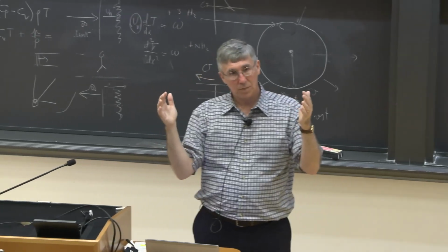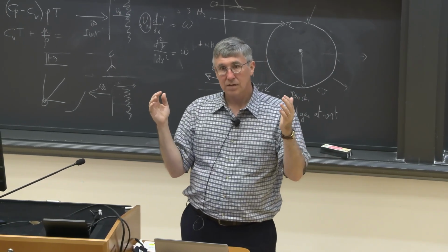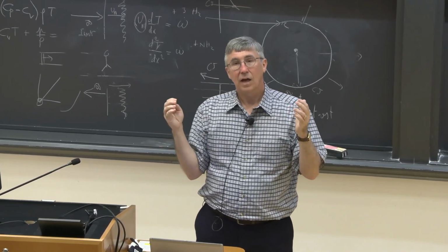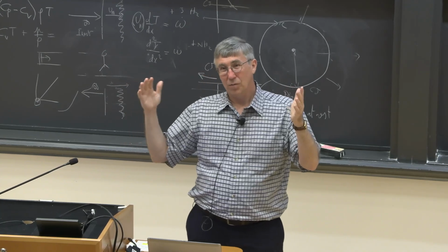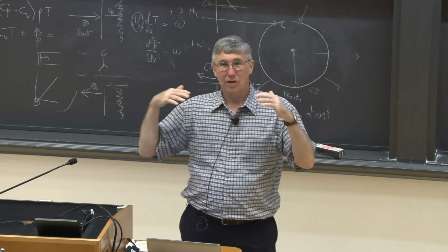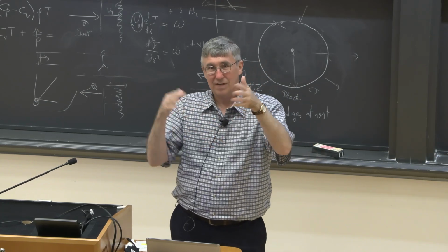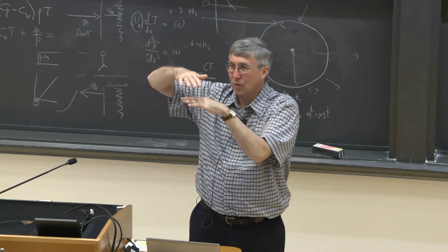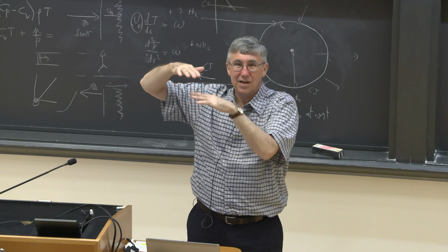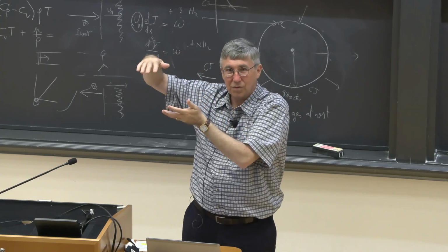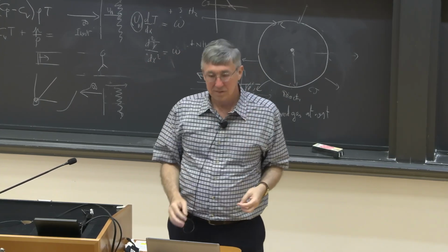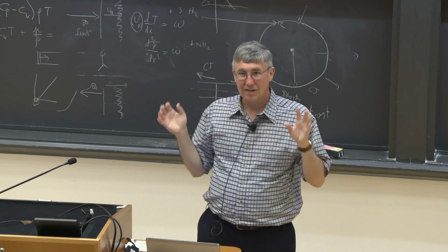So the shock tube measurements are typically about a millisecond or less. You can get really great data. And when you get out to 10 milliseconds, it's starting to get a little bit flaky. And when you get longer than 10 milliseconds, you can't believe it at all because it's all perturbed by stuff like the mixing. And there's also some mixing that happens along the walls. It's not a perfectly smooth flow.